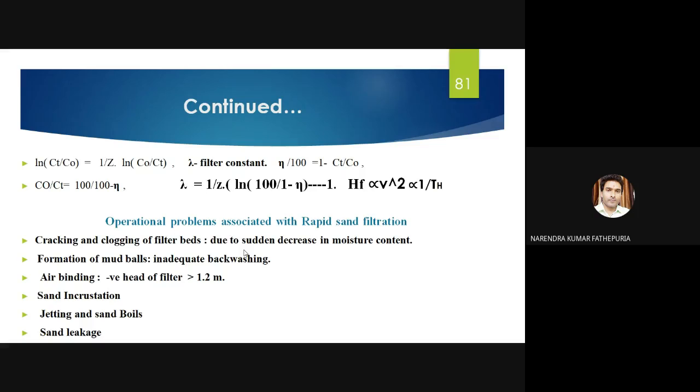These areas occupy the void space of the filter media and drainage system. Trouble is especially likely to occur if the water is saturated or supersaturated with air in solution. The separation of this dissolved air may be difficult due to the following reasons: the negative head pressure due to excessive loss of head, and the increase in temperature of water as it passes through the filter media. These are the problems, along with a release of oxygen by algae also.